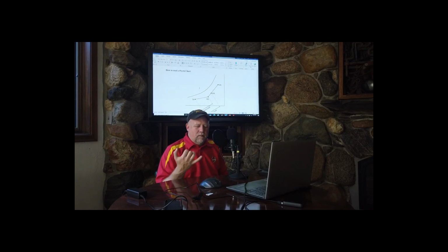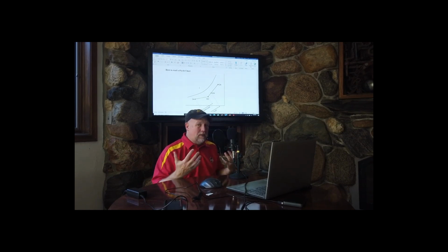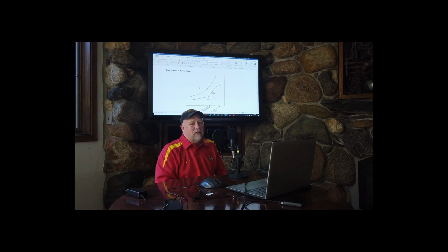Well, everybody is going to be exhaling carbon dioxide. I need to get that out of there. Too high of carbon dioxide levels, and people tend to get drowsy, a little bit sleepy. Starts to smell a little stale, if you will. Not only do people produce sensible energy, they produce latent energy, sweat, a little bit of evaporation off their skin.